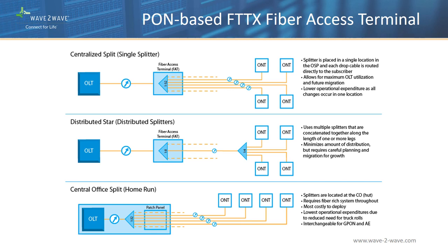In this architecture, end users are connected to one of many PON splitters co-located in the CO. When new subscribers sign up for FTTX service, a patch cord is connected to a splitter with an available port. In this manner, splitters can be populated fully before additional OLT line cards are purchased and deployed. While concentrating splitters solve the problem of efficient population, it raises other concerns, such as dramatically increasing the number of fibers and patch panels in the CO.